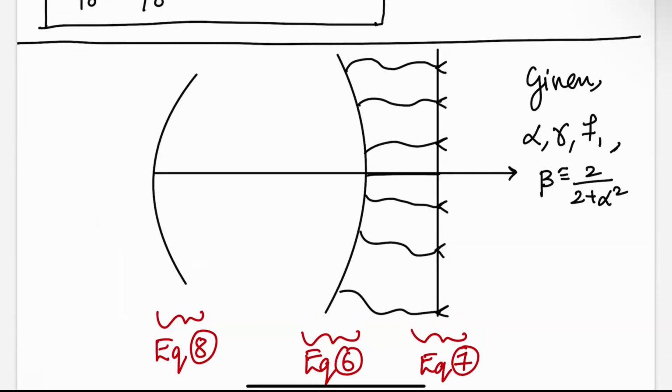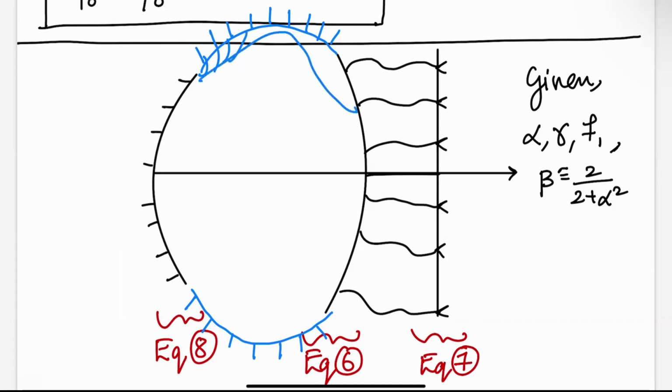So you have some ports that connect out here, and the port locations are known from equation 8. But you also have this region out here, and this region out here and this region out here. Usually what is done is that they place some ports out here and match these ports so that all of the signal going to these ports doesn't get reflected back and enter the output port.